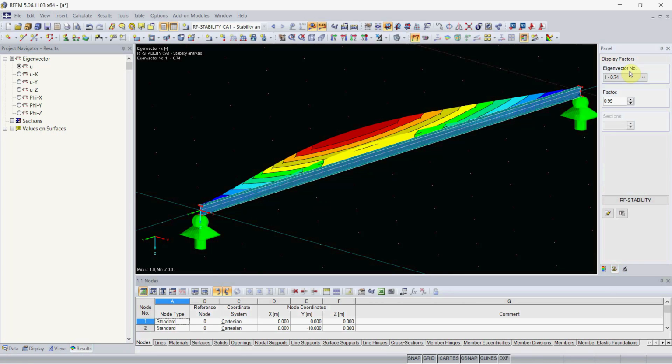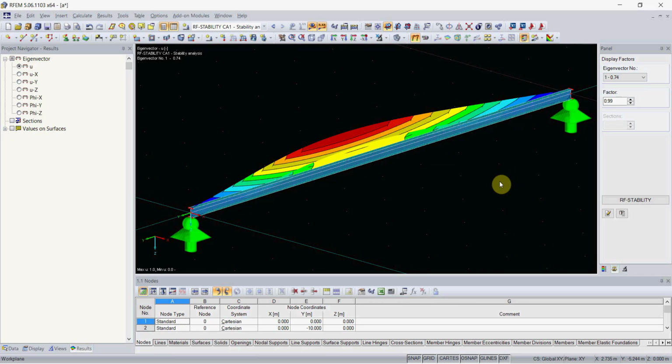You can see now that currently the multiplier is 0.74 and it was 0.85 before, which means that the critical bending moment decreased more than 10% because we changed the support. Of course, to this problem you could use an equation to solve it, but I think it is easy now to see that if you draw your own cross-section, whichever it is, and then you support it in whichever way it is actually supported and load it in whichever load you wish, and then perform the linear bifurcation analysis in RFEM, that would be a stability additional model, you will obtain the critical factor for the loads.